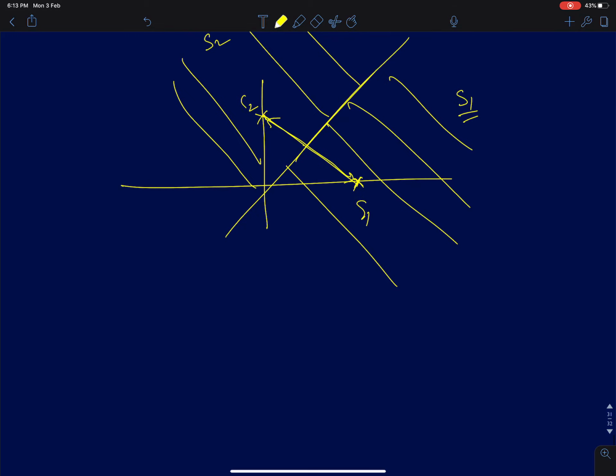It just depends on the distance between the two constellation points, and that will be Q of d by 2 sigma. If we just have two constellation points with equiprobable symbols, it is simply the standard result, Q of d by 2 sigma. This is the optimum value and you are going to get this number.